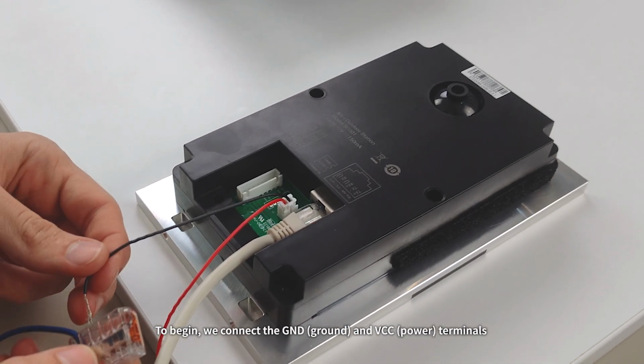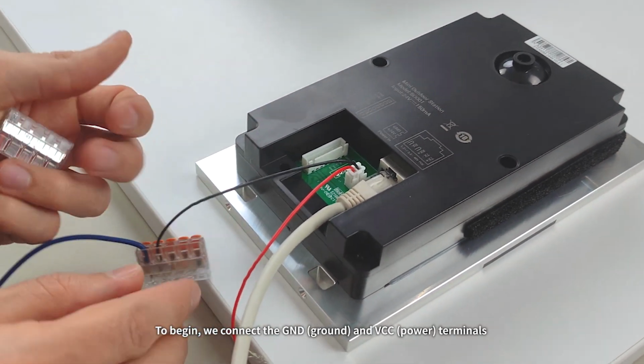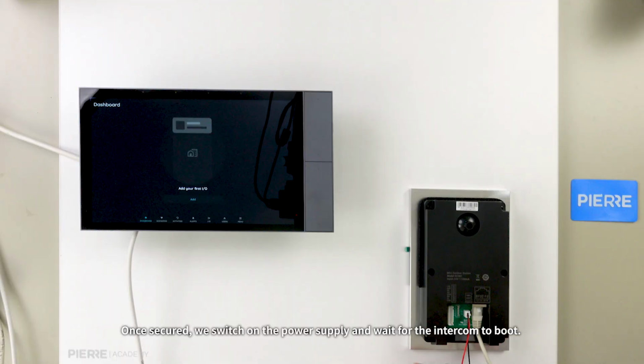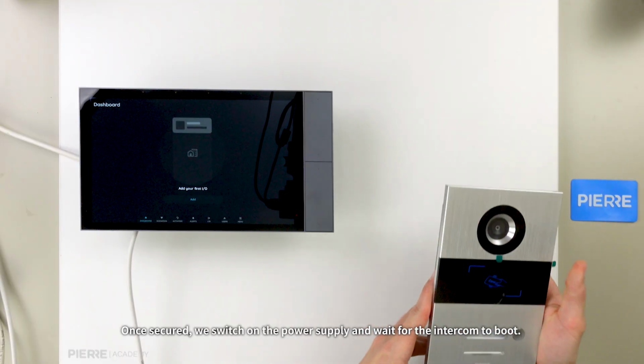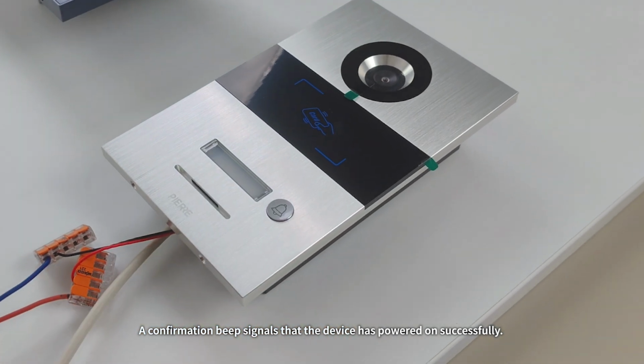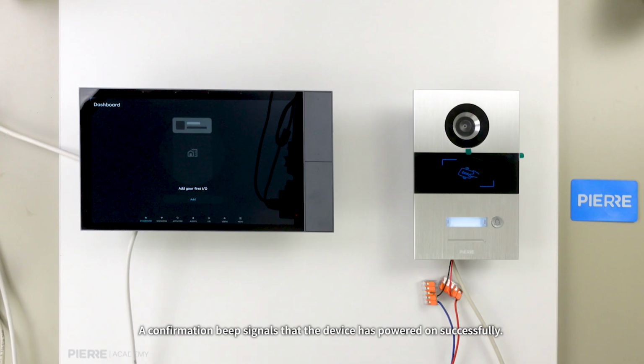To begin, we connect the GND, ground, and VCC power terminals using the Quick Connect terminal. Once secured, we switch on the power supply and wait for the intercom to boot. A confirmation beep signals that the device has powered on successfully.